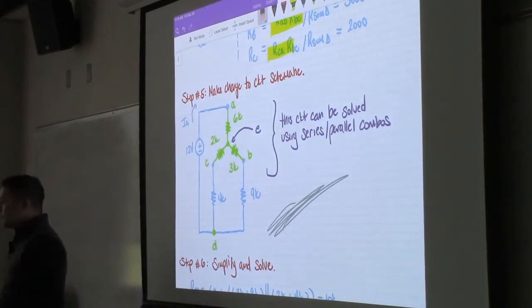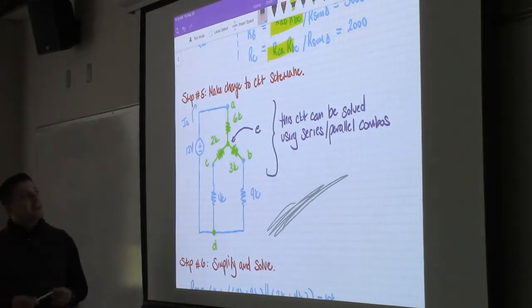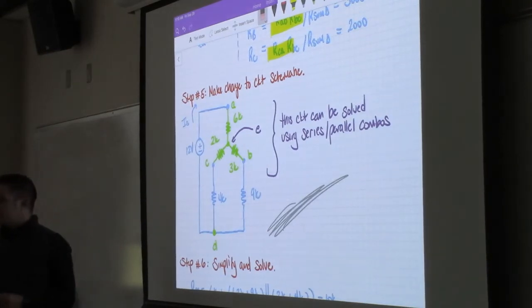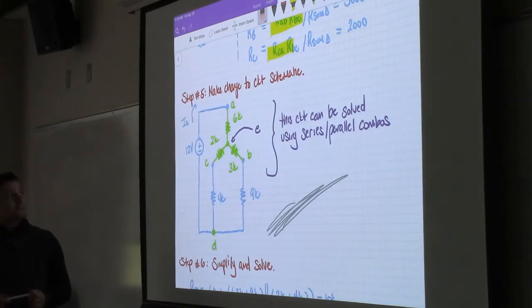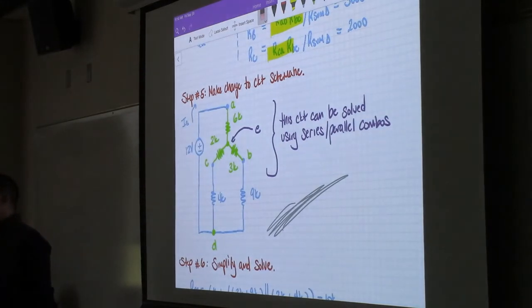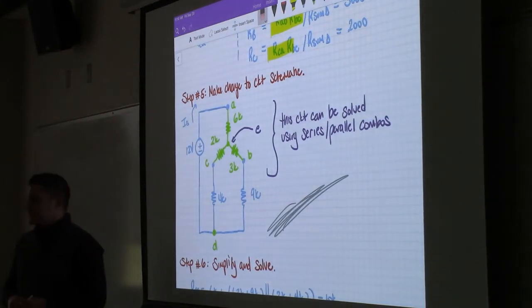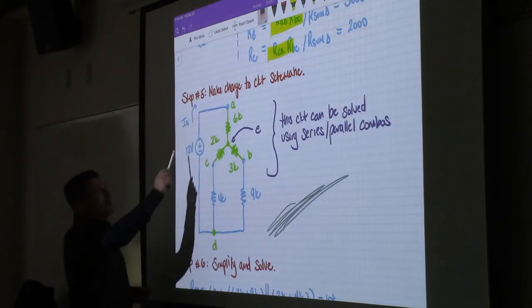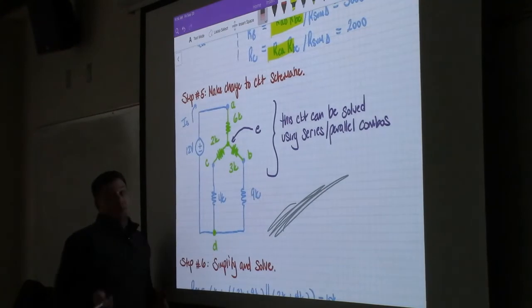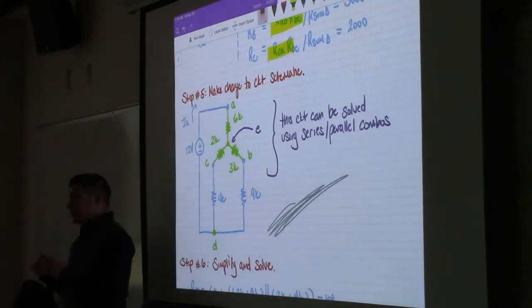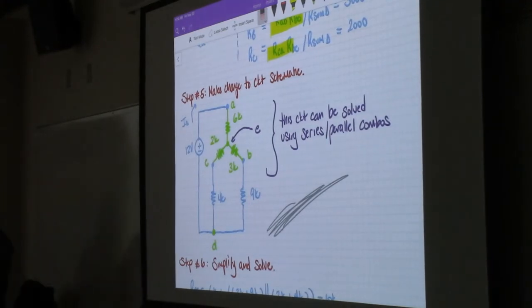Go ahead. You said the current along AB? I take it back, that wouldn't be that hard. I was thinking that you didn't know the delta. But AB, isn't it two different things? Exactly, I'm saying the current along the original configuration. Oh, okay, that was the key. Note that the current IS flowing into that node doesn't change because anything external to the delta or the Y stays the same.